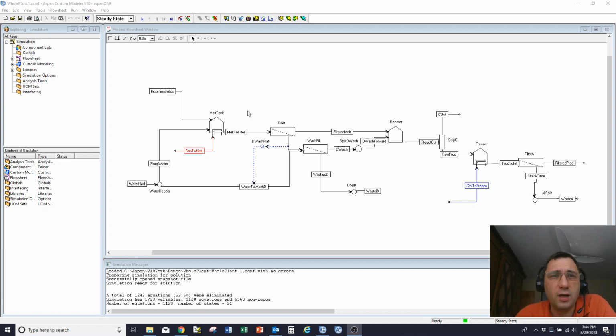Okay, so I've got a fictitious A goes to B goes to C reaction, A being my feedstock, B being a product of interest, C being a waste stream. The A I've got coming in as a solid, molten onto an inert component D. So I want to bring that A and D material together, slurry it up with some water, melt the A off the D, filter the remaining D solids away to go to waste, have the molten A then come to a reactor where A goes to B goes to C.